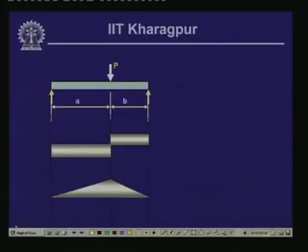You see, this is the shear force and the bending moment diagram of this particular beam, which is loaded with the concentrated load P over the span L, the length of the beam as L. If we have a concentrated load placed at a distance of a, we have the shear force variation. As we have seen, the shear force here, I am sorry, this is negative over here, this is negative, and this is positive. For the bending moment, as we have seen, it is positive for the whole region.